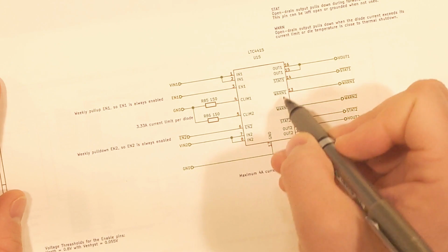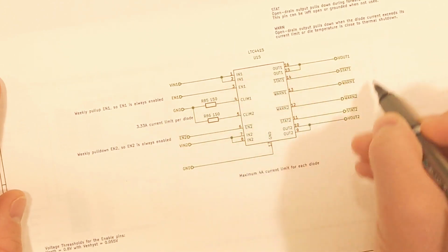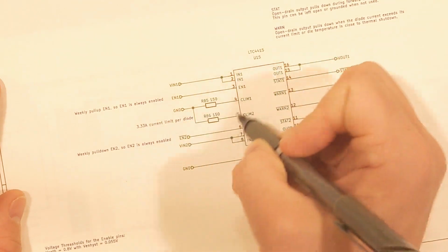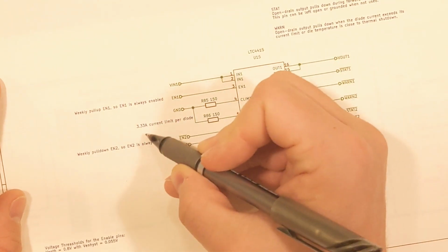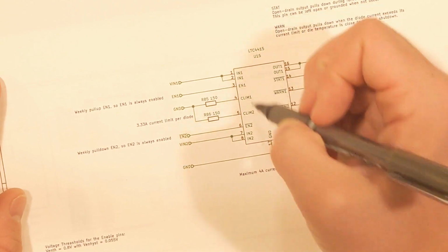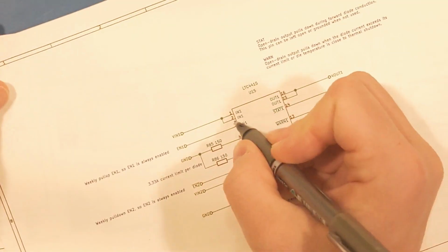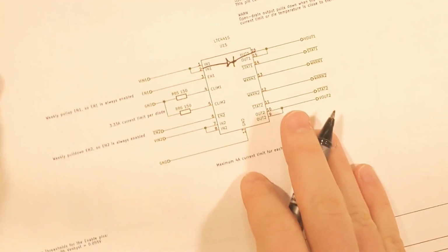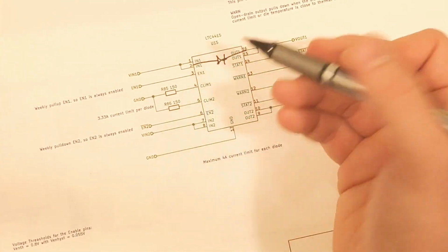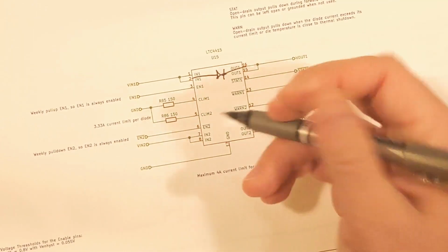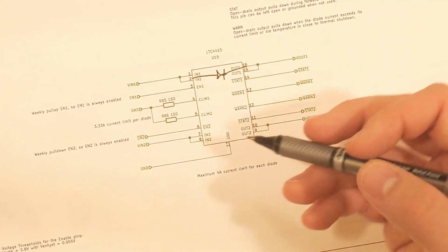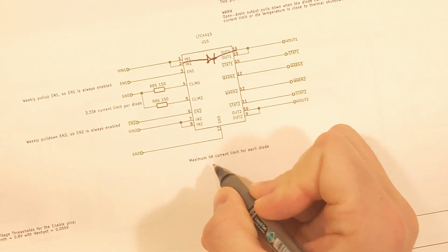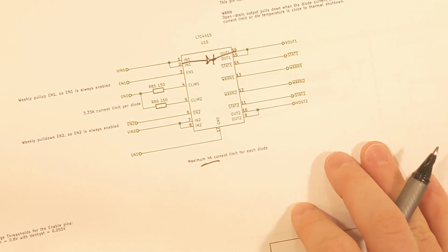Really, this is just a pass-through. VN1 and VN2 just both go in and both come out. There's some warning signals which do get passed to the power management IC, and otherwise I limit the current to 3.33 amps for each of the diodes because these just go right on through. So each of these are limited to 3 amps effectively, and this is something that I can easily tune if I want the current limit higher or lower. I think these go to 4 amps maximum.